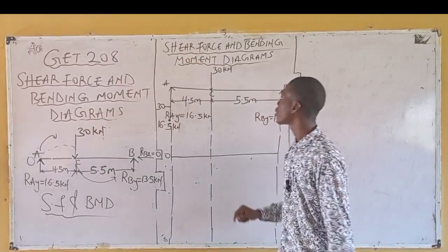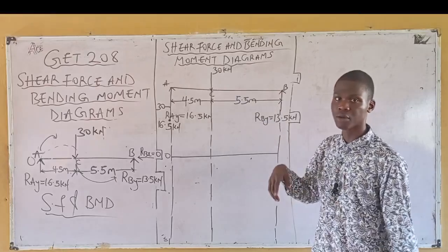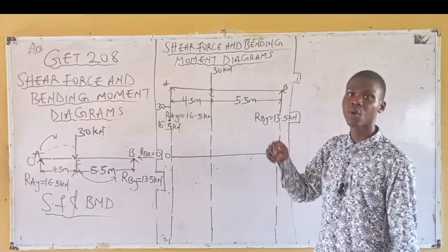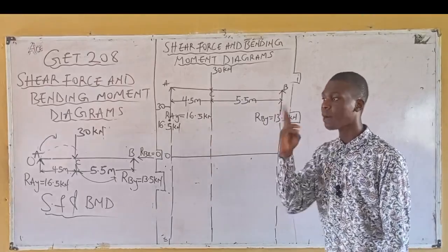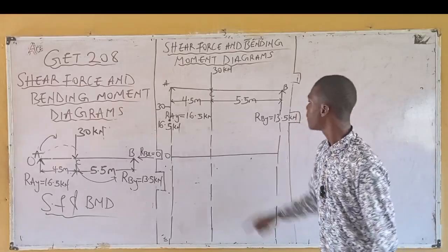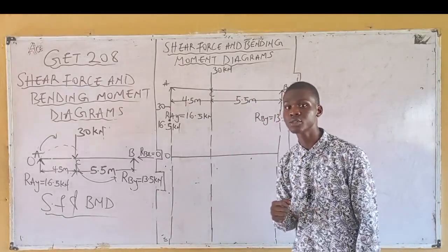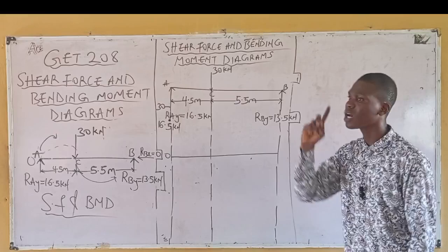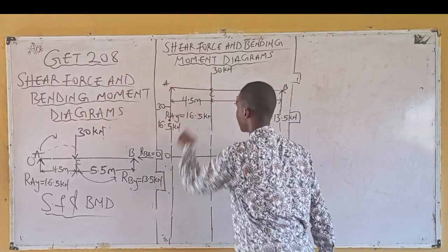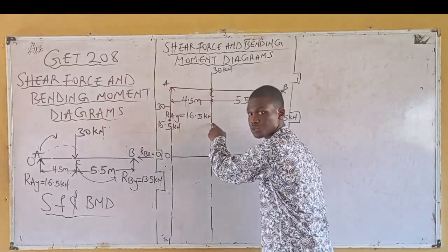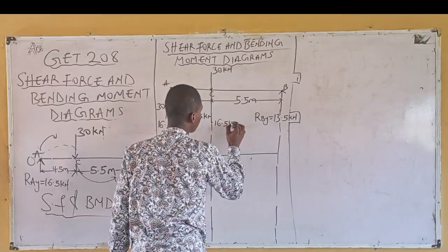No. Now, all right, I said we are plotting shear force value. Go back to shear force calculation, please. At A, what's the value we have there? 16.5. Now go to C. How many values of shear force do we have? 2. Meaning for this very line, which is for C, I'll be indicating 2 points. Now identify what's the first value here? 16.5. If this is 16.5 on A, at C, I'm also having that same point, 16.5, right? So let's say this is this point, 16.5 kilonewton.